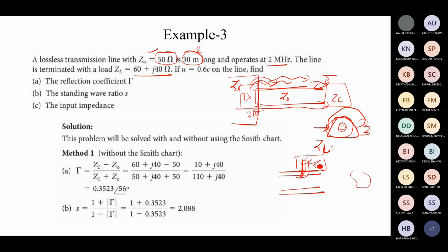You could see that such tapping telephones will be completely different looking, with some big structure naturally. They will have some tuning networks inside, and the phase velocity is given. This phase velocity generally people used to give in order to indirectly define the beta. It is a lossless transmission line, so obviously alpha equal to 0. So first we have defined alpha, beta, and Z0 is given, and the length, so all the important properties are given. So obviously our important job is to calculate the reflection coefficient, input impedance all the way.